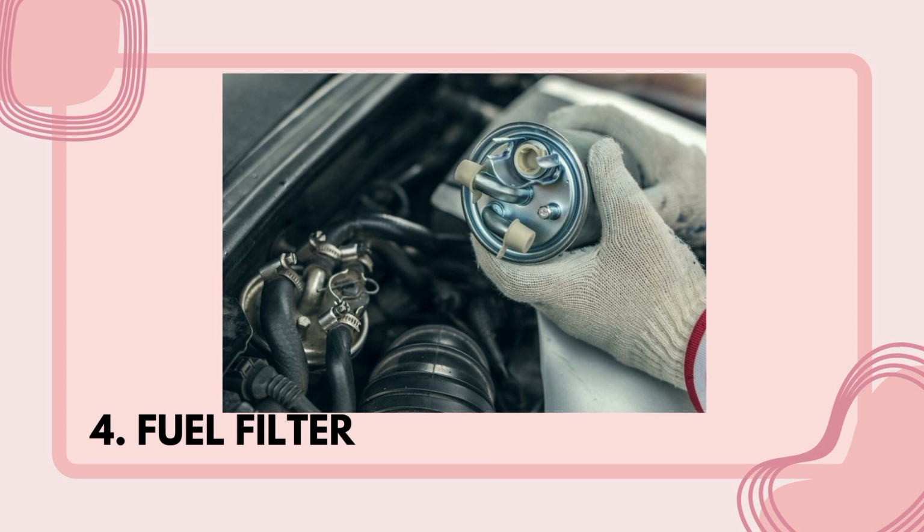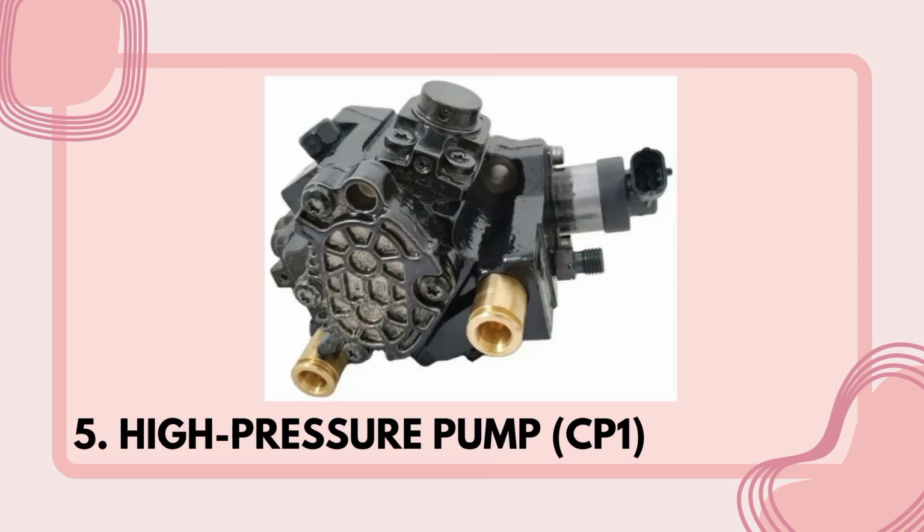Next one is the fuel filter. This is a device that screens dirt, rust, and contaminants from the fuel. The function of the fuel filter is to ensure clean fuel reaches the engine, preventing damage to the injectors and pump. Some filters include a water separator to reduce or remove water from diesel fuel and a heater for cold weather starting.